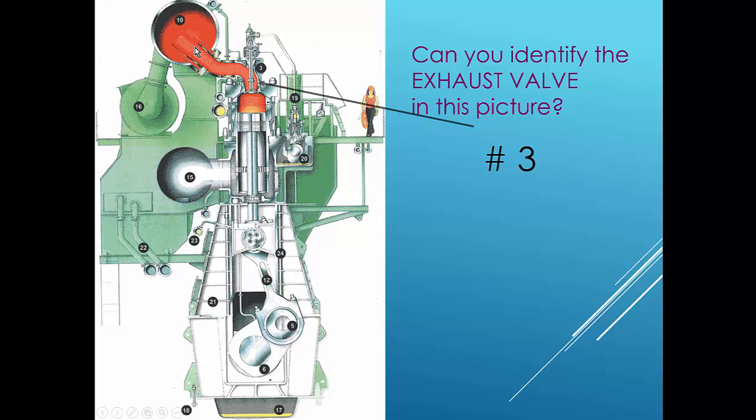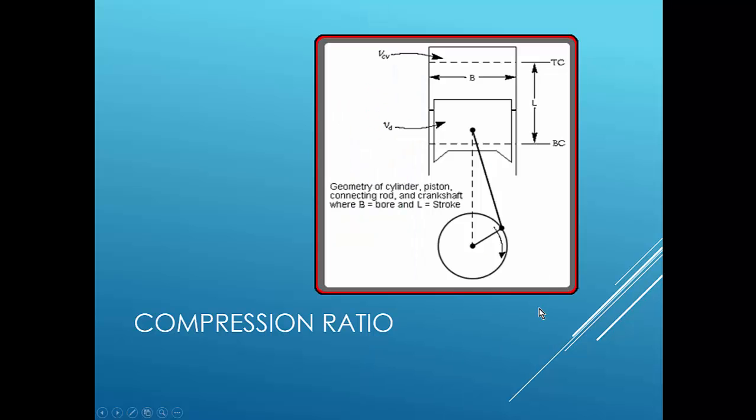We're going to take that excess heat coming off the engine and use it to heat water for accommodation. You can also heat up the fuel, the bunkers, to keep the fuel nice and warm if you're using heavy oil. And you can see here is the intake for the air coming in on this side. Okay, so now I'm not going to get too complicated here.